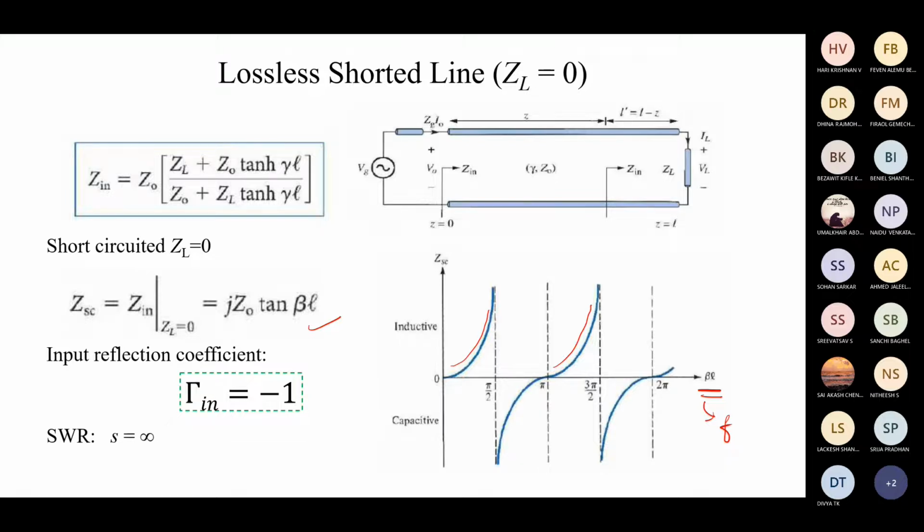Okay. So this is why, if you see the people who are working in microengineering or RF system design or microwave integrated circuits, that is the entire IC which is used to design modulators and demodulators, those kinds of systems we call MMICs, that is monolithic microwave integrated circuits. So in all those circuit designs, people often use this transmission line theory because we can achieve almost any possible capacitance or inductance value simply by defining the length.